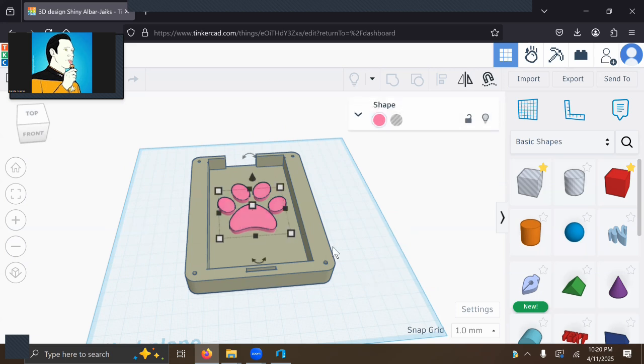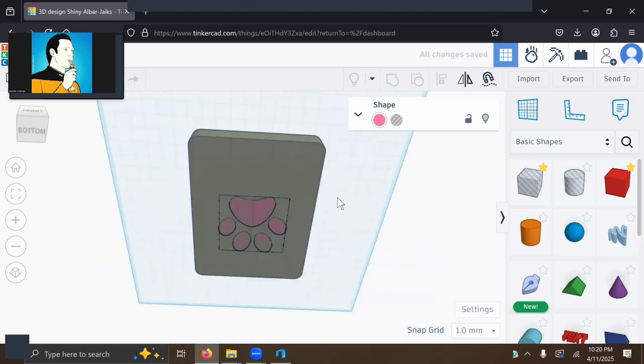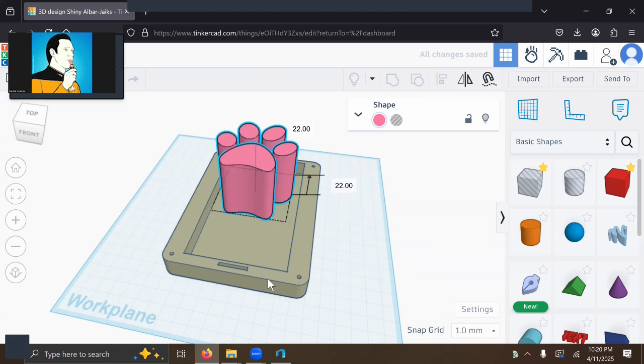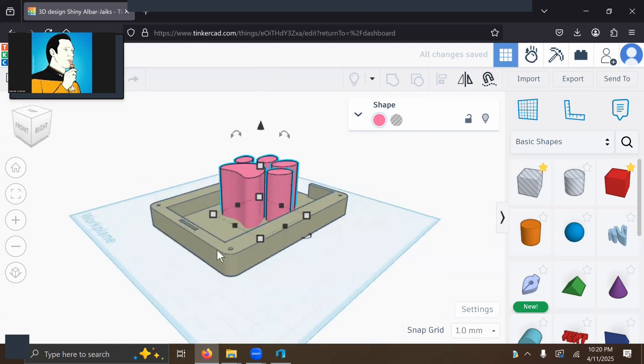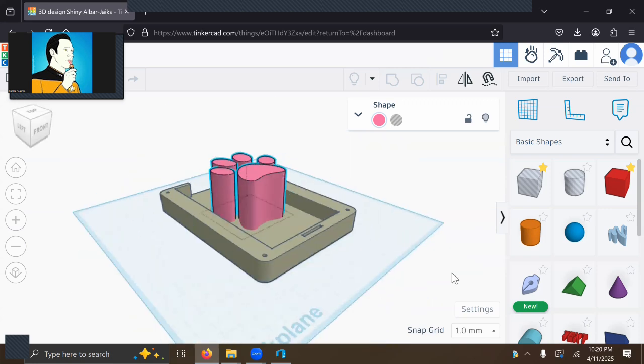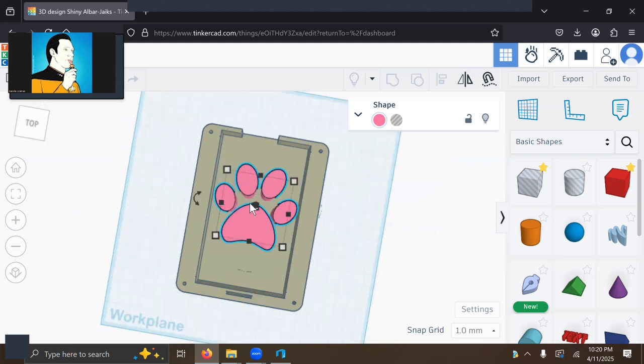If for whatever reason, whatever you're cutting out, it's kind of sunken in, like it's not as thick, this one right here in the middle will let you make it thicker. You need to make sure it's all the way to the bottom, which by the way, if you just hit D on your keyboard, it'll automatically put it flat on the base if it wasn't, or if you accidentally moved it. This is how you move it. So if you accidentally grab that and you're like, oh no, it's not on, what do I do? Just D. D will bring it right back down. D is for doggy. Okay. Right. And make it thicker if you need it.